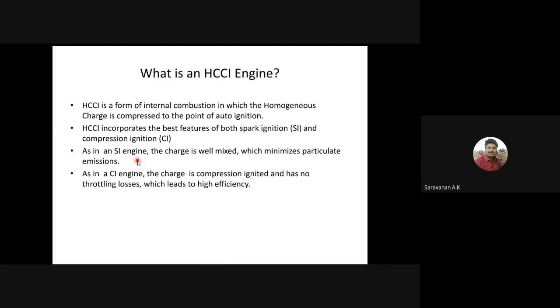In the rich mixture, in these fuel rich regions, the rate of soot formation is high due to the absence of oxygen, which causes incomplete burning. Due to the insufficient oxygen, the burning will be incomplete, so the hydrocarbon fuels will create soot formation.